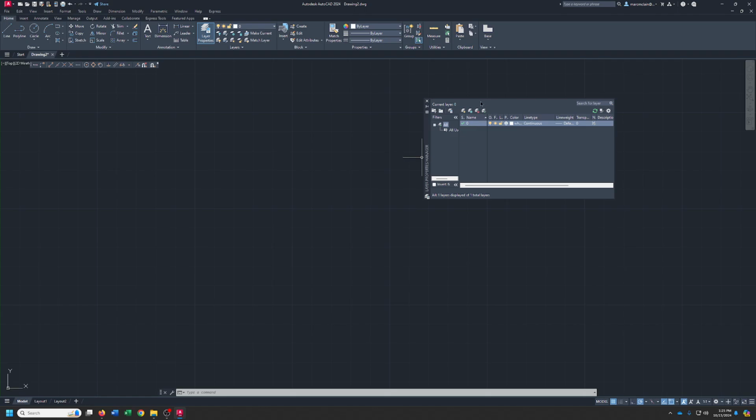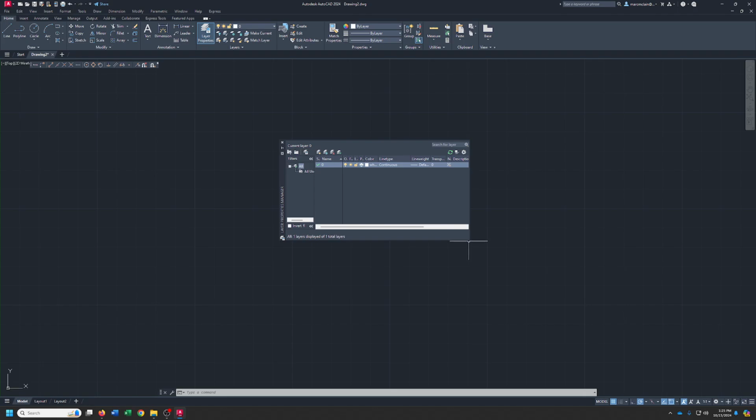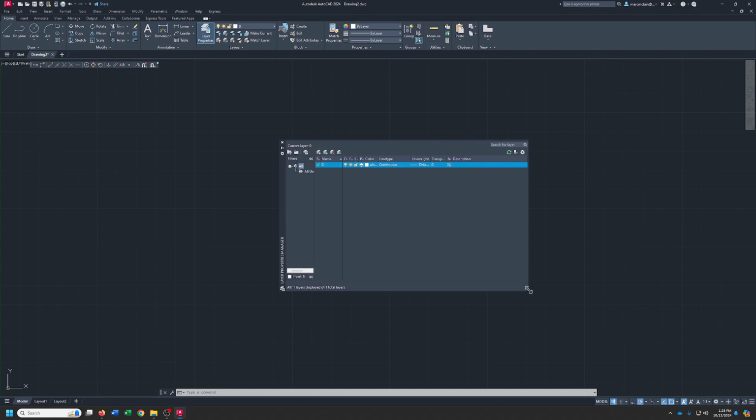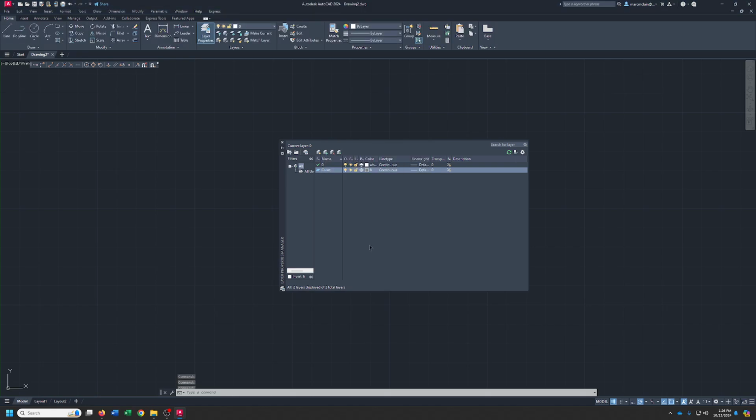We got a kind of a list of layers to make this time. So I'm gonna go ahead and pull this down here, and I will come over in the corner and I'll make that a little bigger. All right, so new layer. We're gonna start with construction. I'm gonna just do that, and we're gonna make that dark gray. Now, once again, your colors are your choice. These are the ones I like. As long as the visibility is basically the same as what I'm doing, you do it the way you want. All right, next one's gonna be object lines.